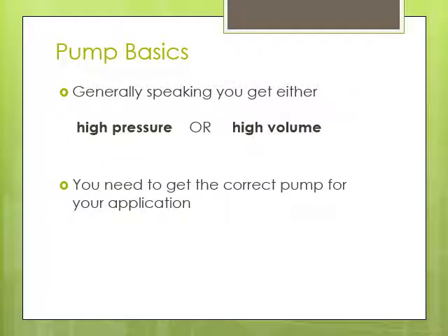So let's go over some basics. Pretty straightforward. We have high pressure pumps and we have high volume pumps. It's almost always very difficult to have both, right? So it's high pressure or high volume. Think of a pressure washer to clean your car. It's got high pressure, but it's not shooting out a fire hose. It's a very thin stream that's high pressure. So usually these two kind of come in opposite relationships. So part of this lesson, actually a big part of it, is trying to figure out what's the right pump for the application. And so right off the bat, there's something for you to feed into your decision.